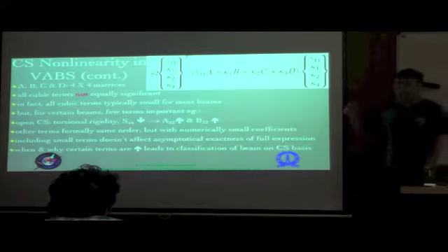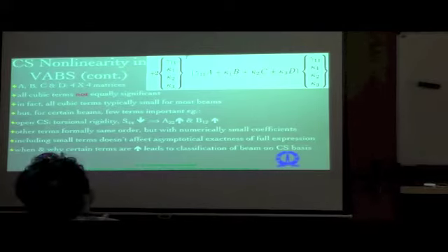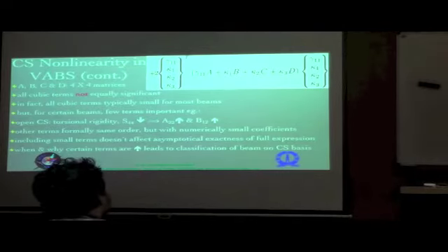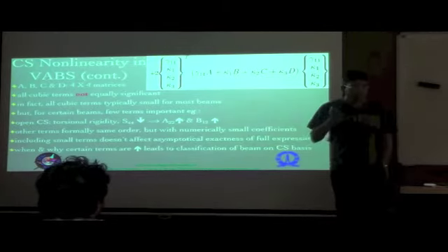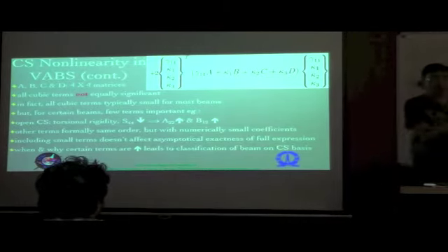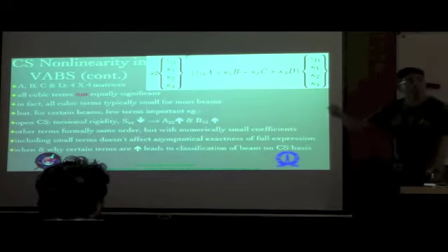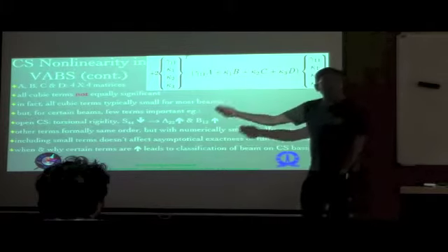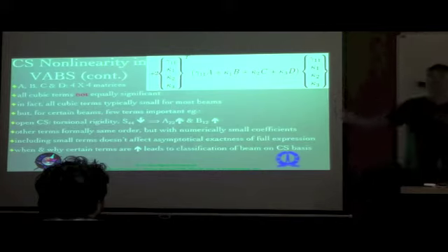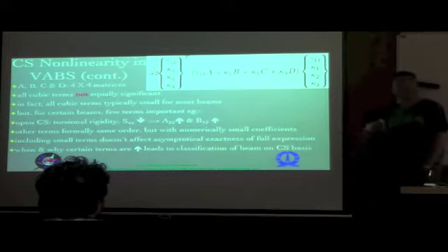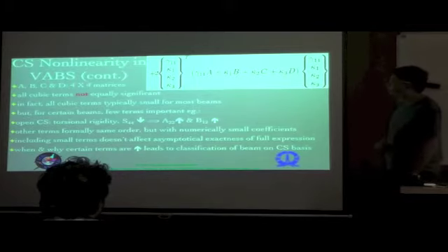Now the question is, we have 6 different cross-sectional stiffness results, or the results for the energy per unit length of the beam that we saw in the previous slide. One is basically the 4x4 classical theory, then you have the 5x5 with the kappa 1 prime or the restrained warping, and then you have the next one which is basically including the transverse shear, and each one of these 3 once again combined with or without the nonlinear terms that you see over here. So you have a set of 3 into 2, 6 different theories.